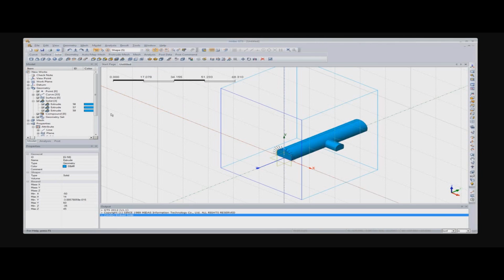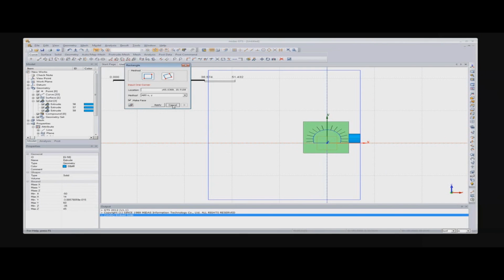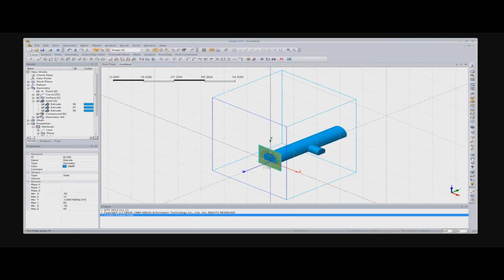Now we have to divide this tunnel into smaller pieces. Because we have to excavate some part and then create the shotcrete, and this goes in this sequence. So for that reason, let me go here, and now go to the curve, creating a new rectangle. This time we ensure that it's the face. Alright, close. If I go to the 3D, you can see this plate is created here.